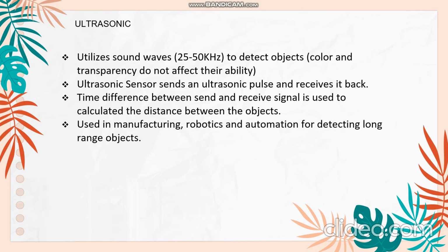Color and transparency do not affect their ability. Ultrasonic sensors send an ultrasonic pulse and receive it back. The time difference between send and receive signal is used to calculate the distance to the object. Used in manufacturing, robotic automation for detecting long-range objects.